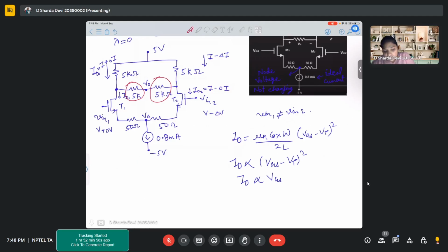But now when we observe the behavior of current entering this node and entering this node, these two are very different and actually exactly opposite to one another, right? So how is it possible to handle two different currents entering from two different nodes in a series combination? It can only be handled when there is a ground over here, right? So if there is a ground at the V0 point, then whatever current is entering from both the nodes can simply go to ground, correct?